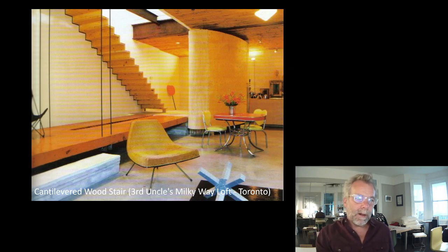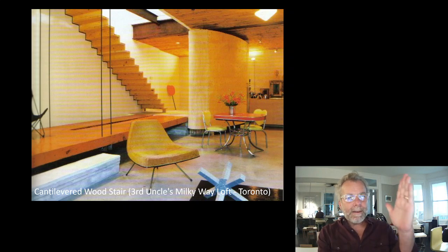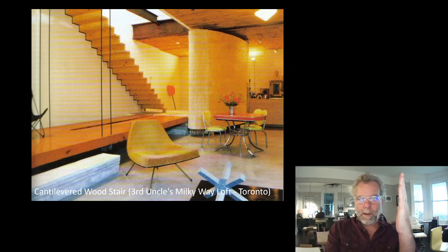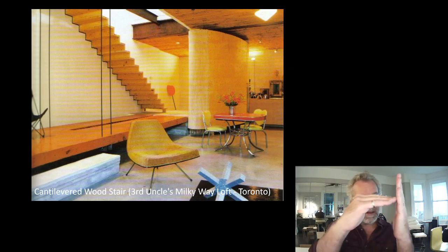There was a block wall. I knew that the block couldn't take the forces. We had no way of connecting wood for big moments like that, and yet this was their objective. What we did, here's your block wall here. We built a stud wall right in front of it, but the stud wall stops at the end of the side of the stair.